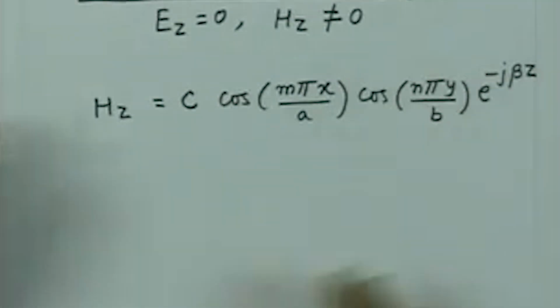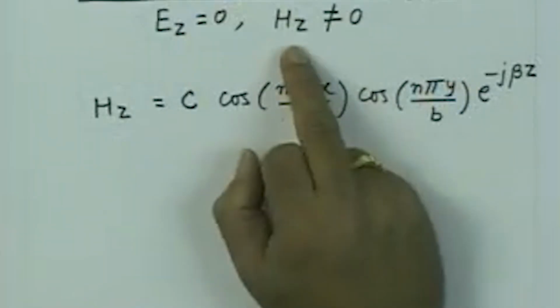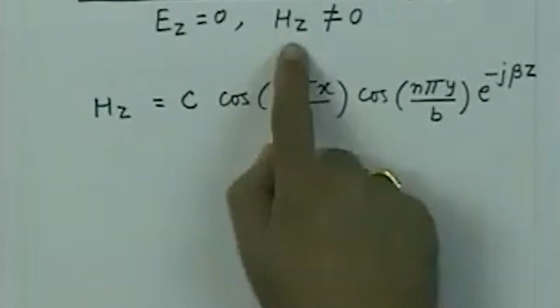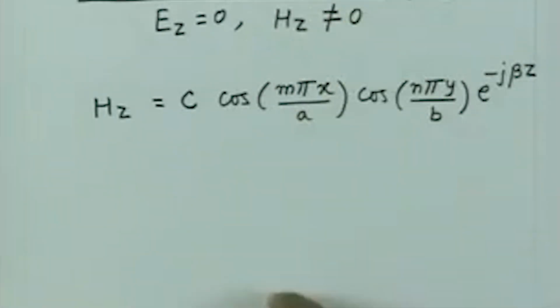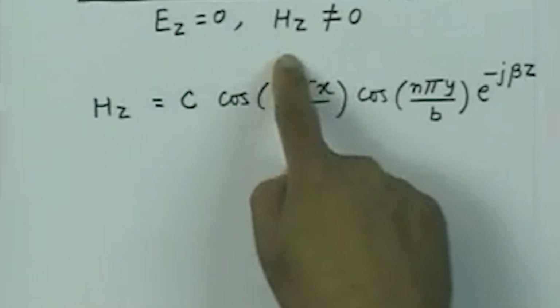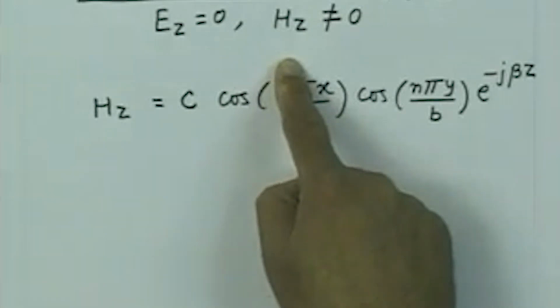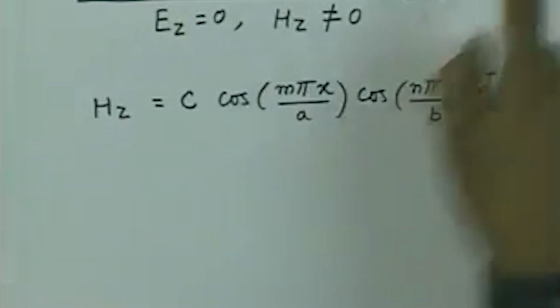So without repeating the algebra which we have gone through for solving the wave equation, of course I can go the exactly same way. I can solve the wave equation now for Hz, then apply the boundary conditions, but note directly on Hz there was no boundary condition. So if I have to go the same routine way, then I have to find out the general solution for Hz, find out the transverse components, then find out the components which are tangential to the boundaries, and then apply the boundary conditions on those components, because for tangential component of magnetic field there is no boundary condition.